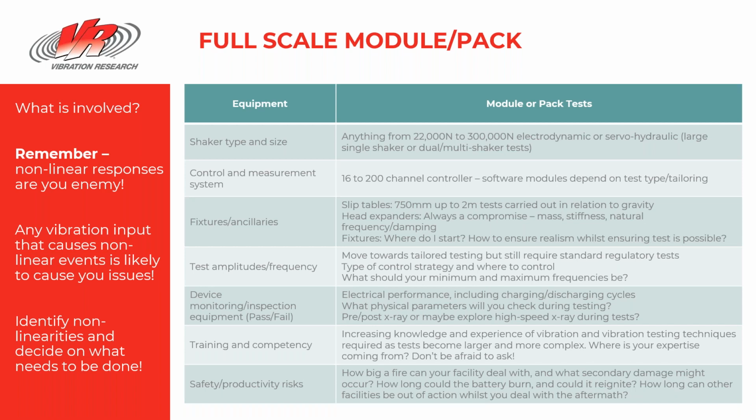Fixtures, yeah, where do you start in relation to realism while ensuring the test is possible? Obviously, you notice a lot of the fixtures that I'll show you in a minute all have the interface with the battery all around its edge, which is where you're getting the highest variation in amplitude with the vibration head expander with its mode shapes. So fixturing is a real issue in relation to how to hold these big battery packs.